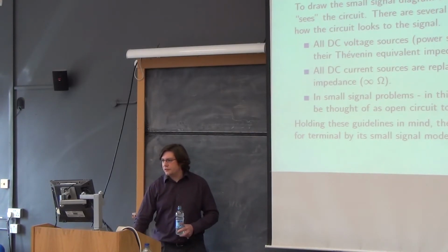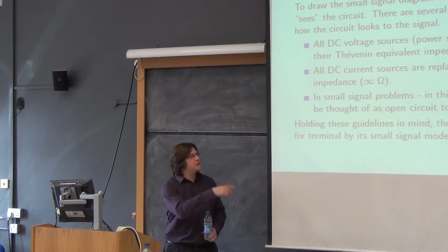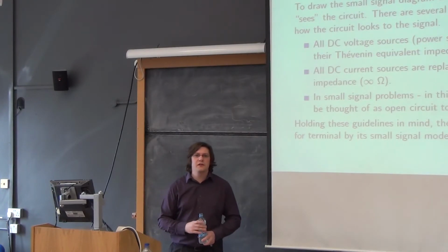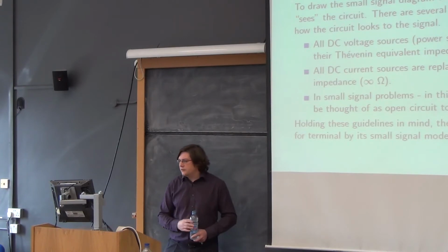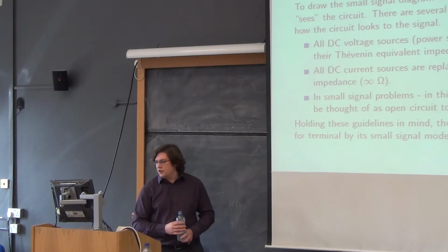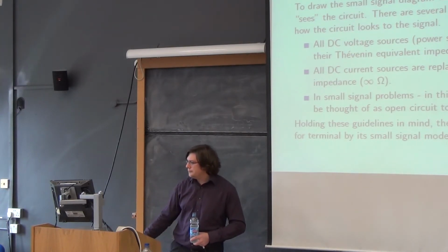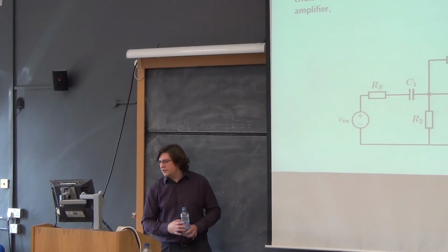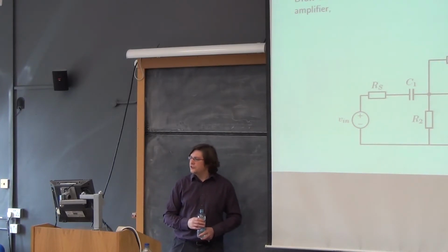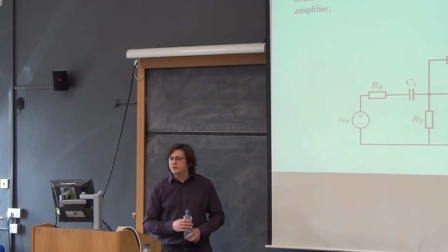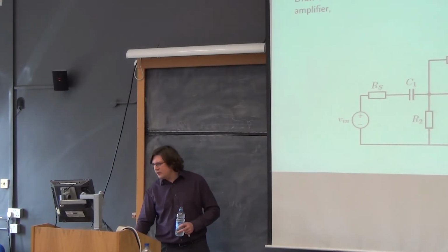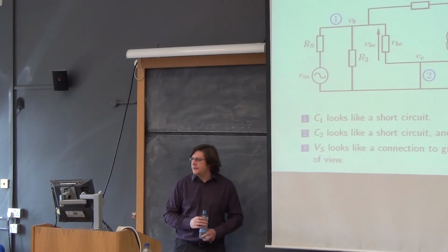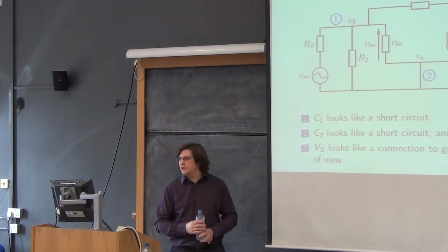You can just go short at all frequencies from a couple of microhertz to light and beyond. So with these three things in mind, you may recognise the first two actually because they come along in superposition as well. With these three things in mind, the transistor is replaced terminal for terminal by its small signal model. So this is circuit number 2 with RE decoupled, and that's what it looks like in small signal terms.